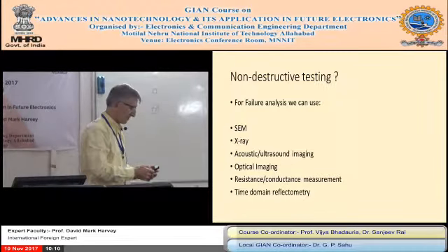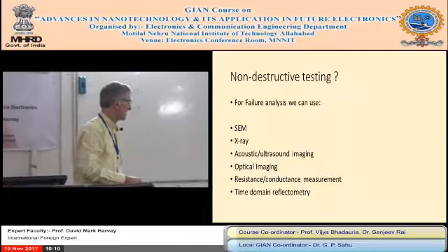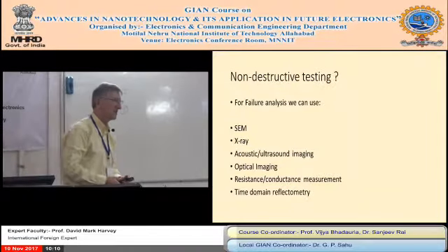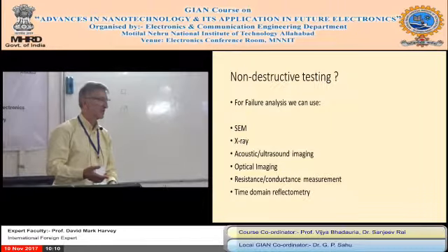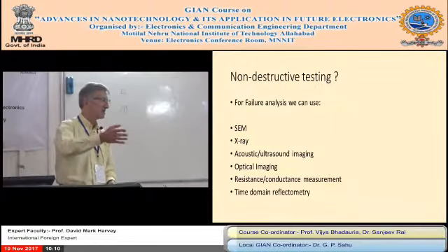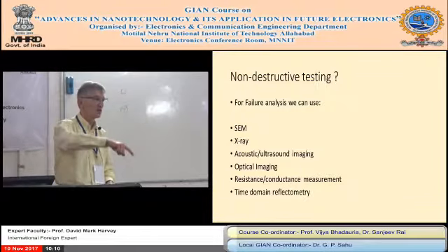So I had some thoughts actually with the Indian lady working for me, but we probably haven't got time in her PhD to look at this TDR, time domain reflectometry. You need very fast circuits, like asynchronous circuits, to find it. We use it for finding faults in cables. You send the pulse down a line, it could be a cable, it could be a circuit board, it could be a chip. You send the pulse down, then you see how long it is to get back.